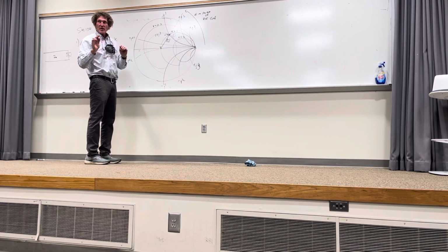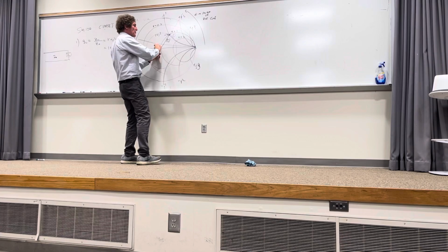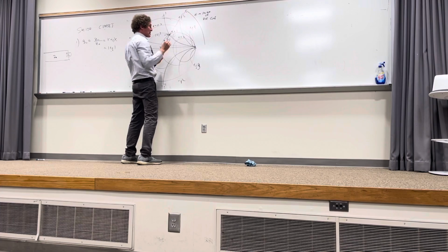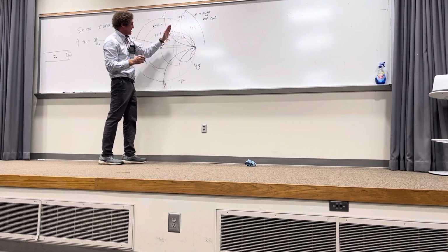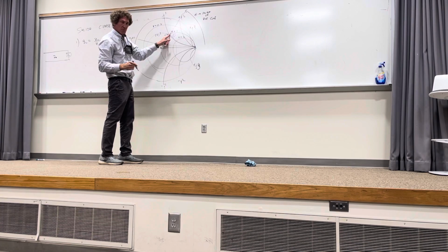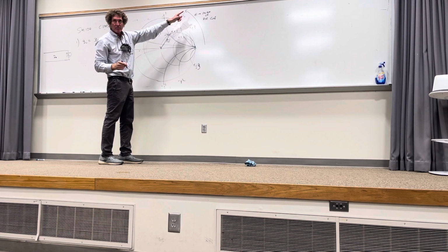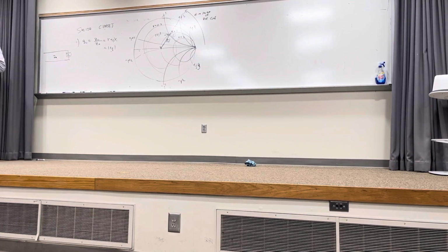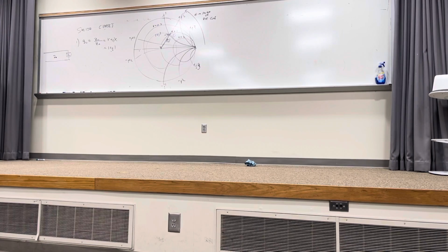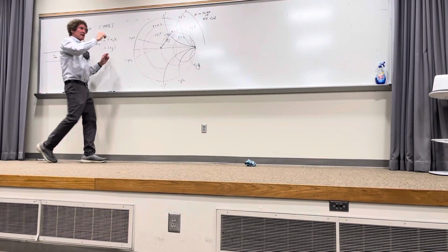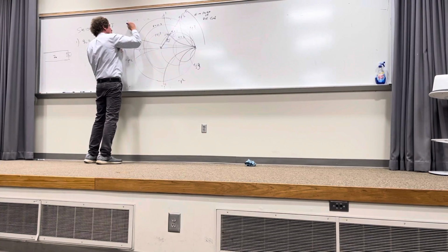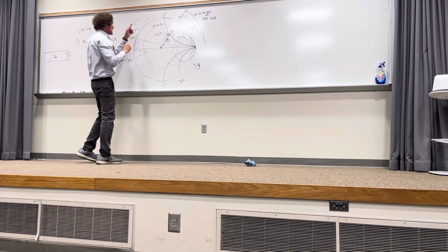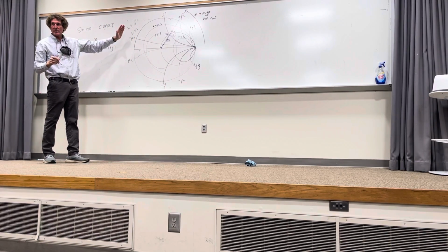Now, take your straight edge and go from the center right through this point and whip it out here, just a straight line from the center of the circle through the point where you entered, and it comes out here. And then you're going to see two things if you look carefully on your Smith chart. And they're near this side of it. And it will say wavelengths towards generator. And then you'll see something wavelengths towards load. WTG and WTL. You're going to see them on the outer rim. Can you all see that?